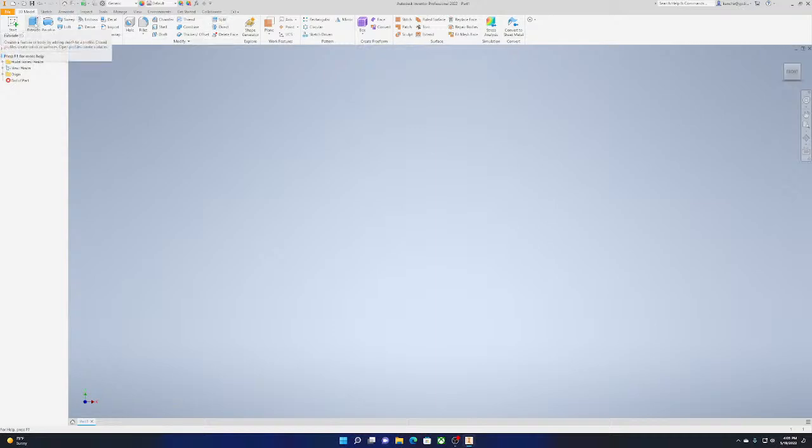We can extrude, which basically means taking a 2D element and pulling it out, as you can see in this little picture. We have revolve, which allows us to create one side and then revolve it around. We can fillet, which basically means to round edges. Chamfer is more of a bevel. You can thread, emboss, rib, coil. These are all our 3D shapes. You won't be messing with a lot of this.